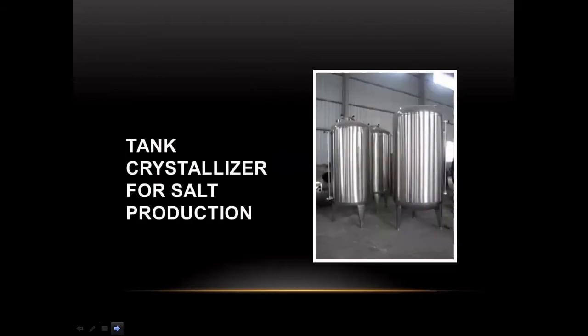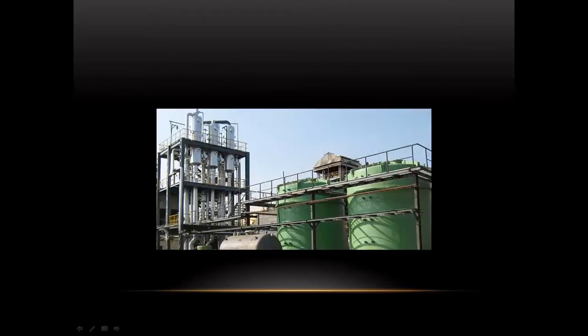Or the usual case is in the production of salts inside tank crystallizers. It could be done that way, or it could be done as in the case of sugar production. Initially, your cane juice is cooked in very tall evaporators. Of course, the purpose is to concentrate it. And then from these evaporators, the solution is dispensed down into the crystallizer units below. The crystallizer induces the formation of the crystals, which are then separated through the use of the centrifuge.